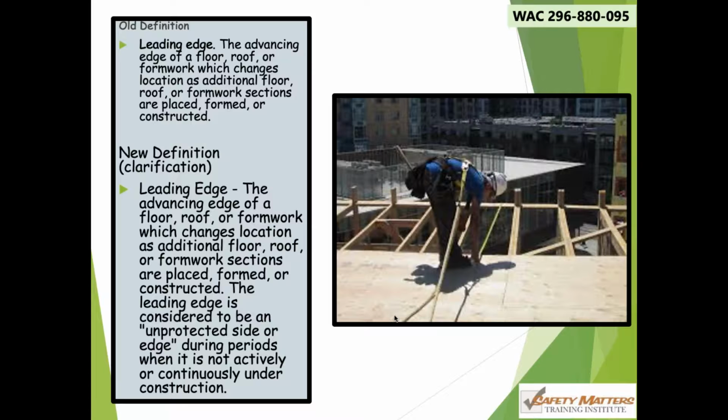Leading edge. Leading edge has always been a bit controversial. Lots of people think that a leading edge is just like maybe standing on a rooftop right by the ledge, and that's not leading edge. Leading edge is a verb. It's an activity. You have to be performing leading edge. It's not just standing somewhere static. So they changed the definition. LNI had to clarify some things.